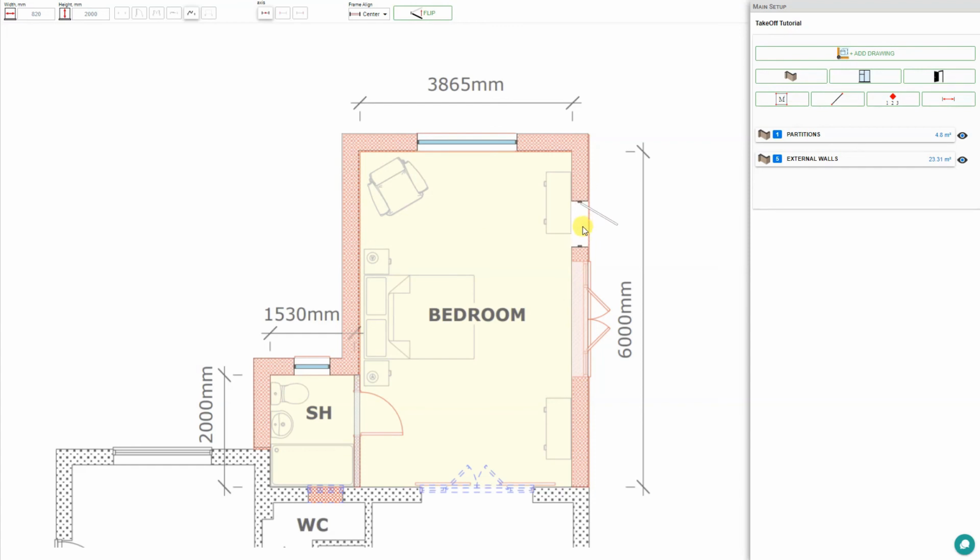And then as we hover over our floor plan, the tool automatically snaps to our existing walls and rotates the door to fit appropriately. So we'll place this over the floor plan where the door belongs and click to place the door. But before it's completely finished, we'll need to click a second time so that we can position the door opening. So in this case, we'll click here. And then we can position a second door. And so here we will position this one here and adjust our opening.